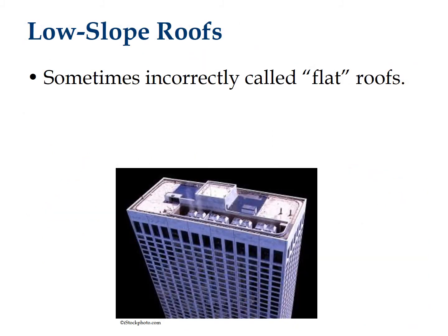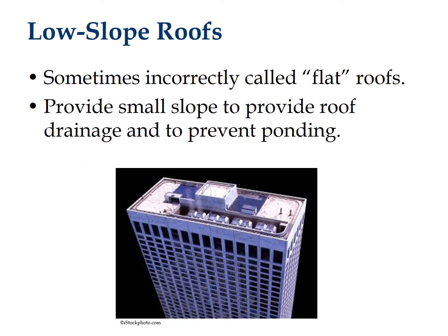Low slope roofs are not flat. They are slightly sloped to roof drains so that water will not stand or pond on the roof. Because water moves slowly on low slope roofs, the roofing material must be highly resistant to infiltration.